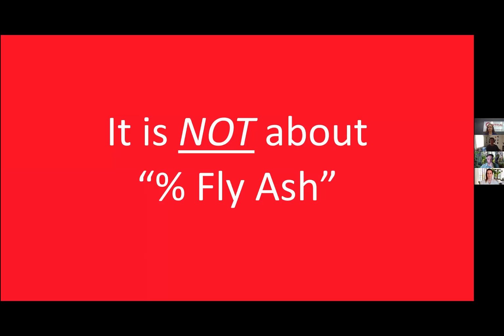A key that I want you to take away from all of this, because a lot of people specify this way or think of it and say, are we using fly ash? It is not about fly ash. Reducing the embodied carbon of concrete is about reducing the embodied carbon of concrete. It's not about putting fly ash or slag or an SCM into the mix. If you do need a proxy, you might use the cement content.